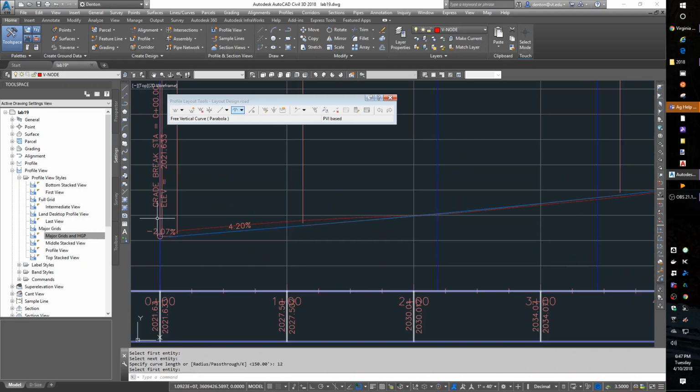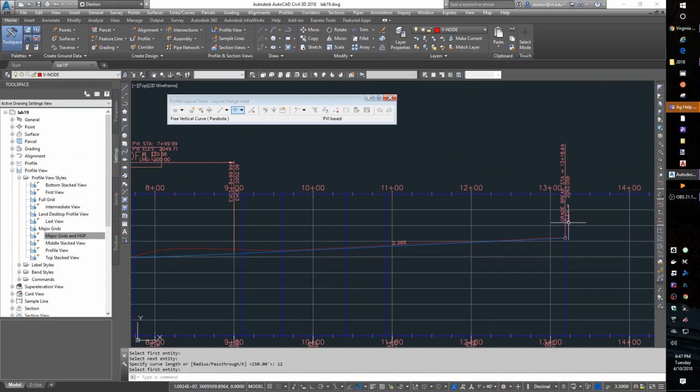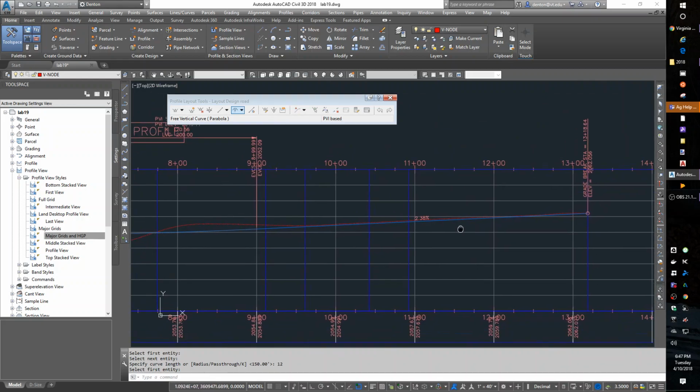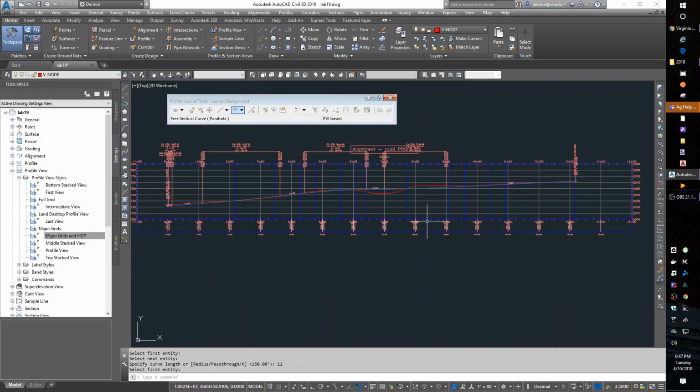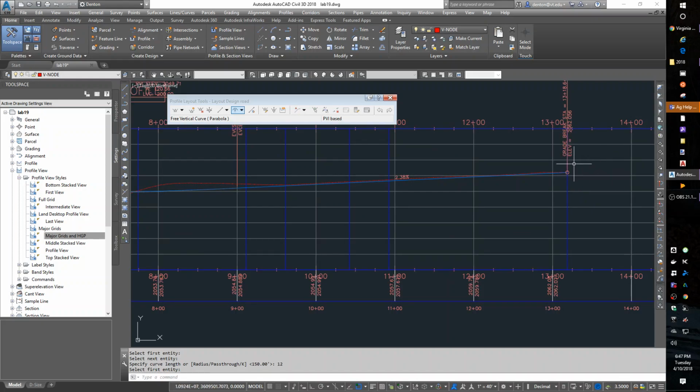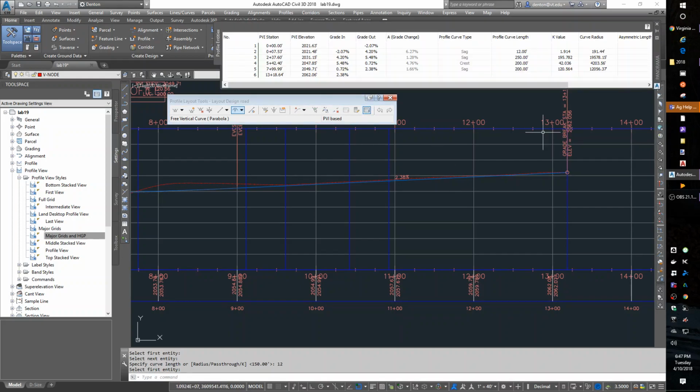You want to make sure you're snapped in at the beginning and snapped in at the end. Now, if I need to, let's say, finish up lower at the end, like I want to be 6 inches down or a foot down, I can go into my grid view and say, oh, that last PVI, let me see, station 1318 PVI, what if I don't want the 62?